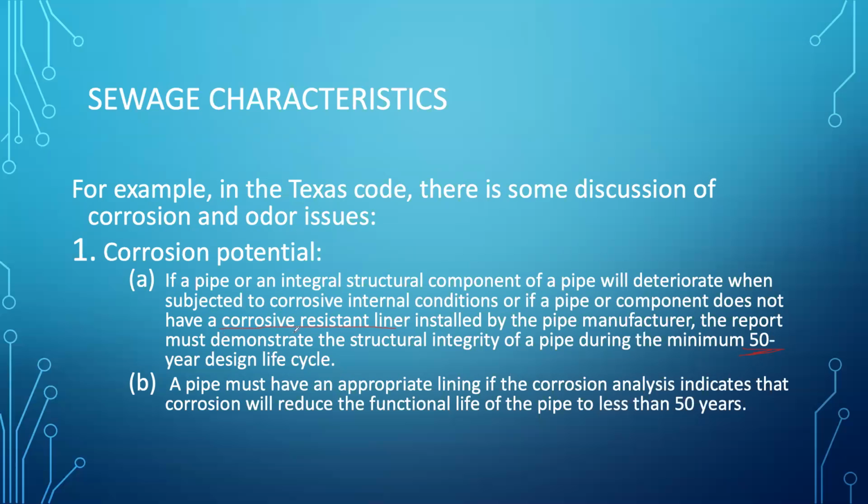Mostly what that's led to is almost uniform specification of corrosion-resistant liners, or where applicable, departure from using reinforced concrete and using high-density polyethylene and various other polymer-based pipes, which at one time we were just guessing that they were corrosion resistant, but we have well over 50 years of practical experience now in their use, that they're generally considered to be pretty effective sewer pipes from the standpoint of corrosion resistance.